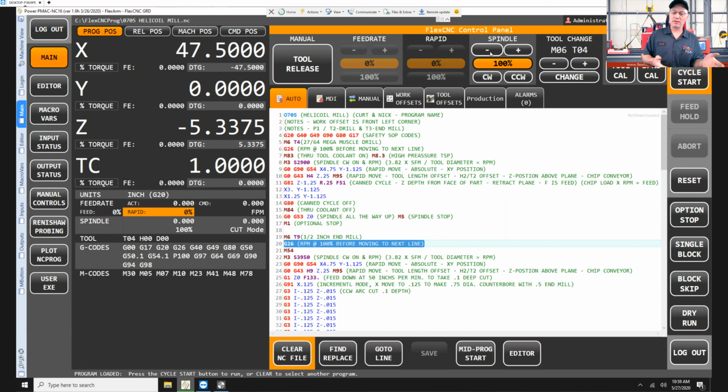If you have a gearbox and you're at 1500 RPMs and you drop down to 20%, it's not going to let you drop down below 1,000 because the gear change is at 1,000. You can come down to 1,000, but until you actually tell it to go into a lower gear, boom, then from there you'll go lower yet. It's just a matter of working with the gearbox to determine whether or not you're going to be down to that point or you have to go lower.